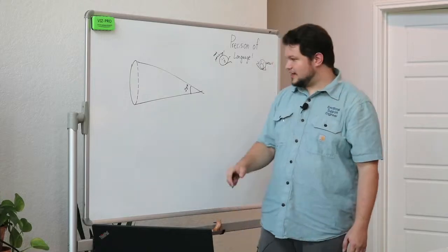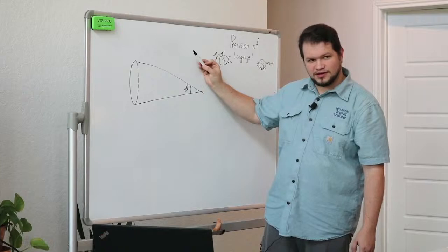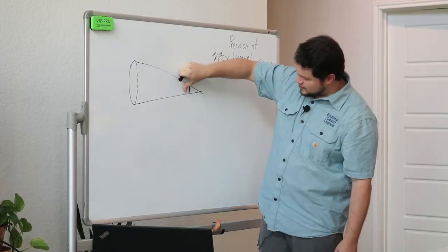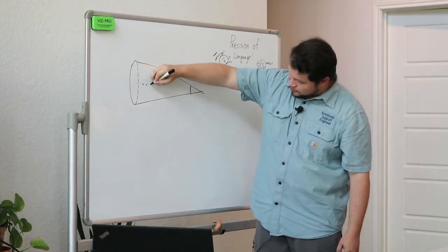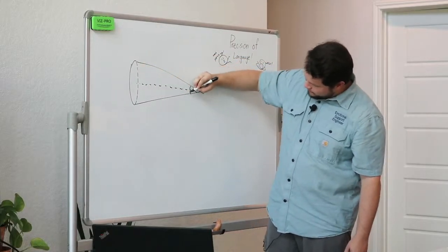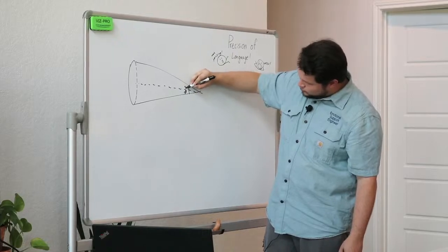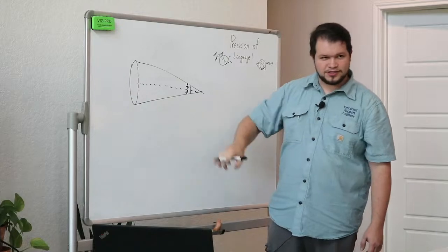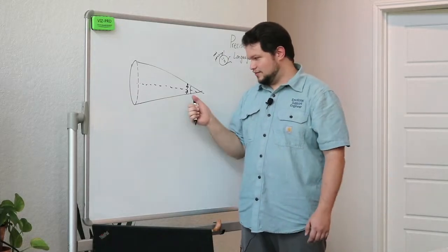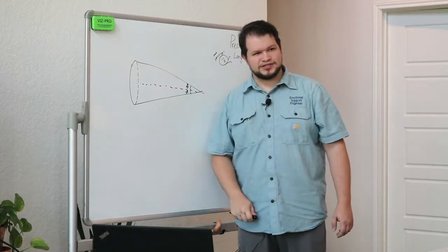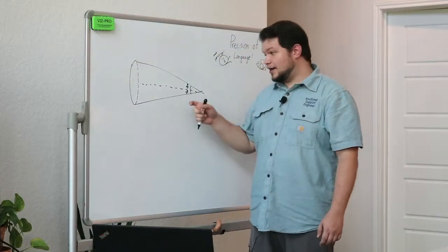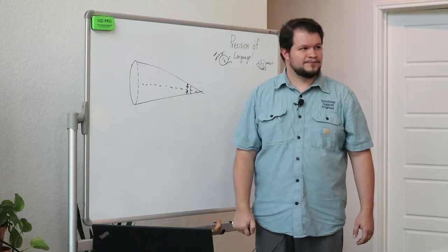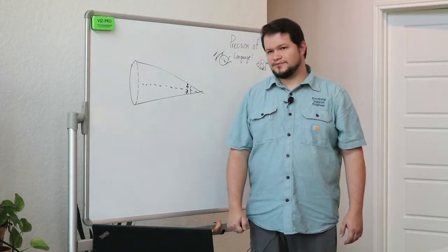It is possible that it is not in what's called an inclusive angle, which is the whole thing. It is possible that, if I drew a center line here, it is 25 here and 25 there, which is called exclusive angle. I did not look at the spec hard enough to see. I looked at the website first page where it says it was 25-degree field of view. I don't know which one it is. It could be either one of them. So that is a good question. The spec sheet would tell you.